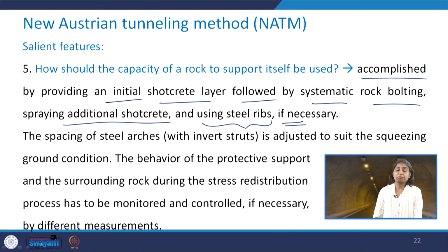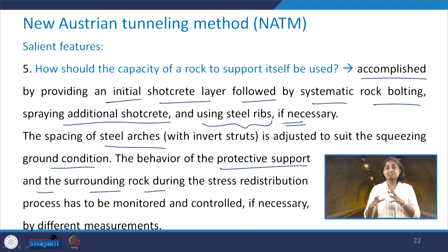Again, this will all depend upon the quality of the rock mass and the type of excavation. The spacing of steel arches within the inverted struts is adjusted to suit the squeezing ground condition. The behavior of the protective support and the surrounding rock during the stress redistribution process should be monitored and controlled by means of different measurements.